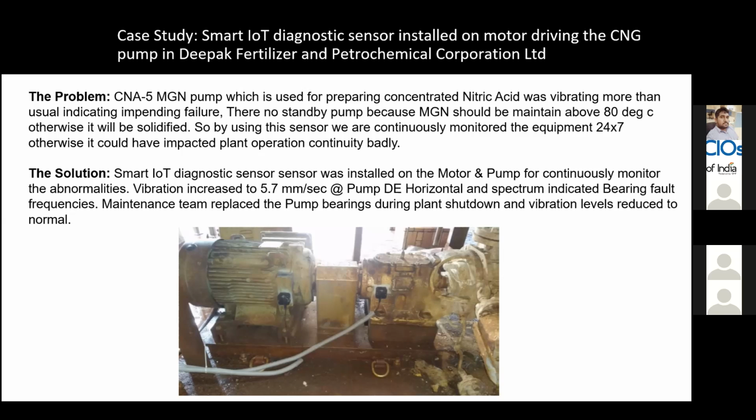This was one of the critical equipment. One incident happened: the coupling failed previously in December 2019. The coupling was damaged, and only the motor was rotating. The pump was not rotating, and this had a big impact.